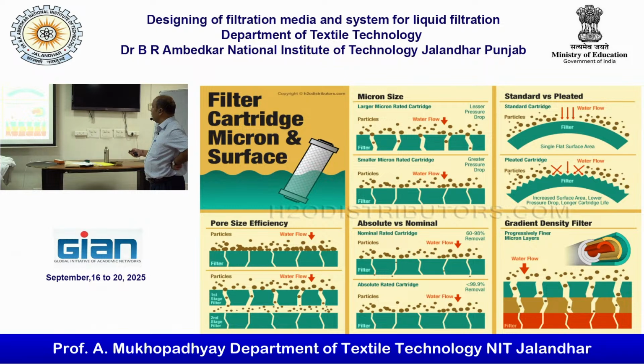Here, if you want to remove large micron rated particles with the cartridge, then there is lesser pressure drop. If you are going for a smaller micron rated cartridge, there is greater pressure drop. That I have explained already. Another aspect is absolute versus nominal rating. Nominal rated cartridge means 60 to 98% removal of a particular size. That is known as nominally rated. Whenever I say absolute rated, that means it will be 99.99% removal. Absolute rating is possible in the case of woven fabric, as I told, whereas non-woven fabric can be used for nominal rated cartridges.